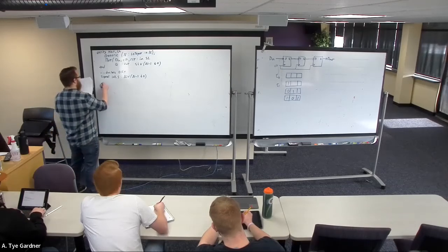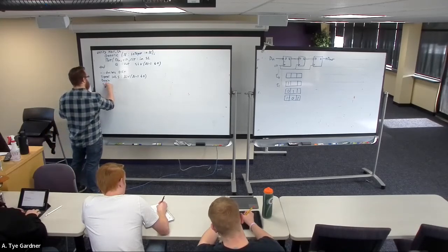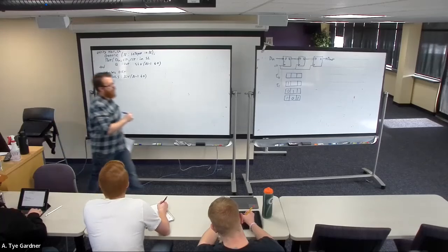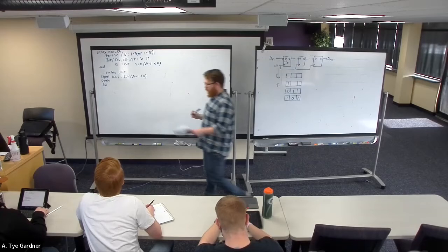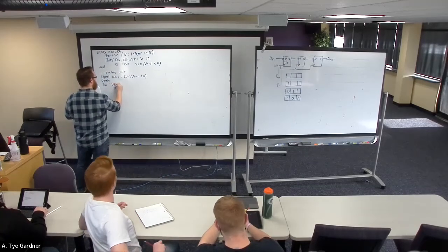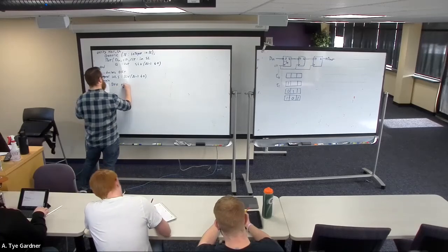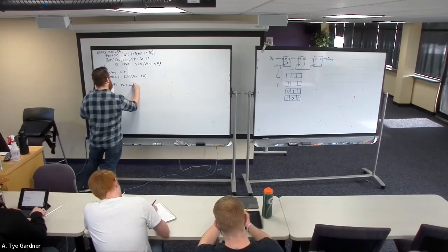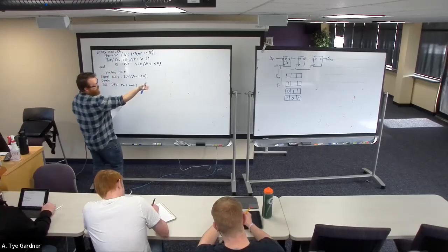Then I need to, after the begin, make my shifter 0, my first one. I'm going to call this guy S0. So my F0 is my D flip-flop, and it has a port map. This is the first one, right?